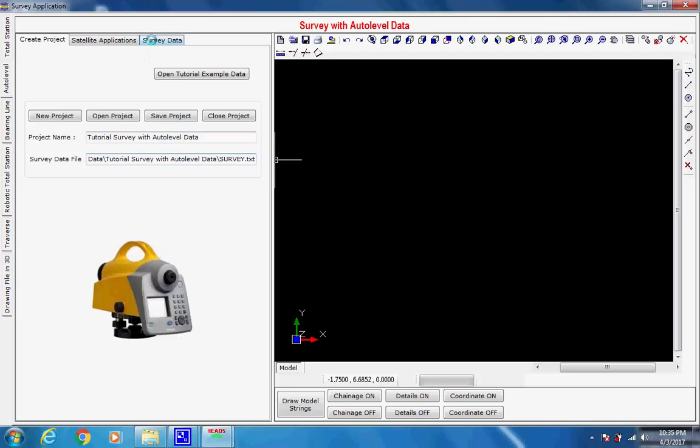Only the survey base plan drawing by digital mapping will not be created from ground model, which needs total station data for reading various features like houses, drains, electric poles, boundary walls, etc. on the ground. The alignment passes through the center of the cross-section, thus alignment becomes the center line of the survey. Alignment is defined and created as Halen, which means the horizontal alignment.